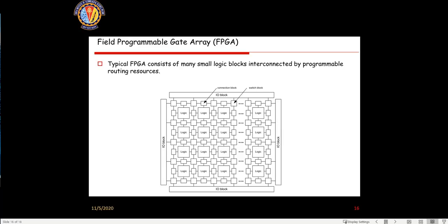Yes, sir. Okay. So when we do the program in an FPGA kit, we do the Xilinx program, and before we dump the program into the FPGA, we will also specify, like this FPGA kit will have 16 pins, right? When I say input A, there is something known as floor planning, in which I specify input A is pin number 1, input B is pin number 2, the output will be from pin number 16.